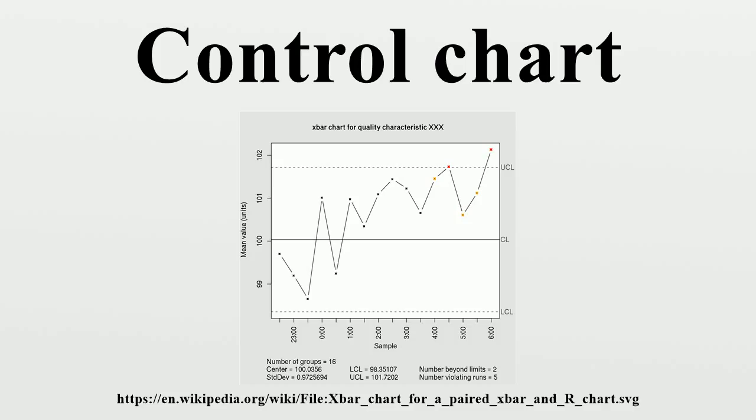Meanwhile, if a special cause does occur, it may not be of sufficient magnitude for the chart to produce an immediate alarm condition. If a special cause occurs, one can describe that cause by measuring the change in the mean and/or variance of the process in question. When those changes are quantified, it is possible to determine the out-of-control ARL for the chart. It turns out that Shewhart charts are quite good at detecting large changes in the process mean or variance, as their out-of-control ARLs are fairly short in these cases. However, for smaller changes, the Shewhart chart does not detect these changes efficiently.